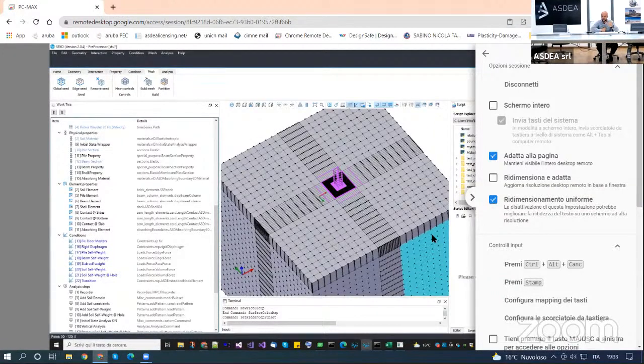It's also useful to understand what happens if you use a mesh that is larger or smaller than a certain frequency requires, because at the end of the day, when you apply an earthquake, first you will not be able to visualize if the solution is correct, because you have a continuous set of waves entering the system. So you need to do some benchmark before. In this way, you can play with it and understand what happens if I take an earthquake and select a range of frequencies in which I'm interested, and I don't care about the others. Otherwise, you will need extremely huge models. So you need to find a compromise.